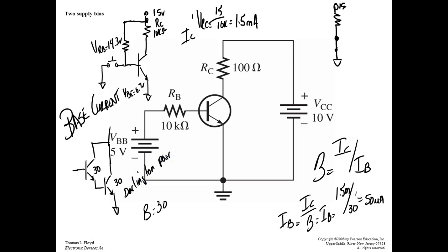This arrangement has been around so long, you can buy these guys. You can buy them. All you need is 3 leads. It looks like a transistor because all you need is this lead, and that lead. And the transistors are hooked together inside the block. Looks just like a transistor. But they're called Darlington pairs. You're going to look at these, and they're going to have betas of 1,000. I've seen them with a beta of 10,000. Very easy to get a beta of 10,000, right?